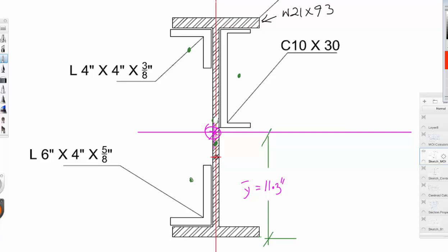So for the I-beam, I need to find the x distance, which is this here. It coincides with this one, there is no x. The x is just minus 0.0079. That was the x bar, because this x bar is measured from the center of the web, and the y distance will be the vertical distance between the centroid of the I-beam and the centroid of the entire thing, this distance.